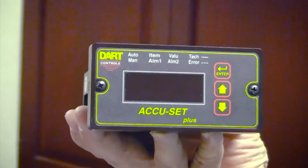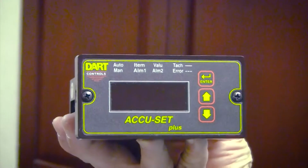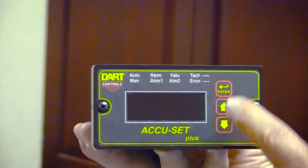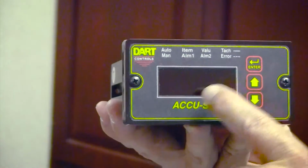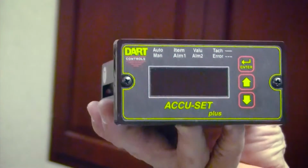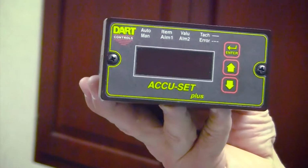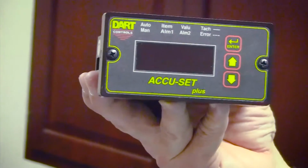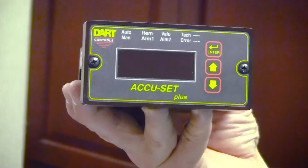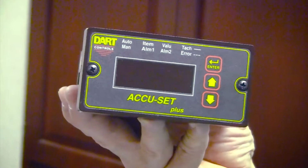That means you're adjusting a value. You use the up and down arrows to make that adjustment. Once you get it to the value you want, you press the enter button. You'll return to the item list. The value light will go out. The item light will turn back on. You navigate the item list using the up and down arrows, or if you're finished, go to item 0, press enter, and you'll be back in the operational mode.